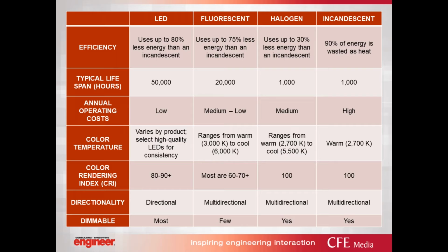So integral LEDs, which are LEDs built into fixtures rather than retrofit lamps, generally are 50,000 hours plus. A lot of them are even reporting 100,000 hours, 200,000 hours, and so on. So that's one real takeaway in terms of maintenance. Facilities are finding that it's a much easier source to maintain since it lasts so much longer than other fixtures. The annual operating costs are much lower. Again, maintenance is a large factor in that, as well as the general wattage being used. So your energy bills are going to be much lower.